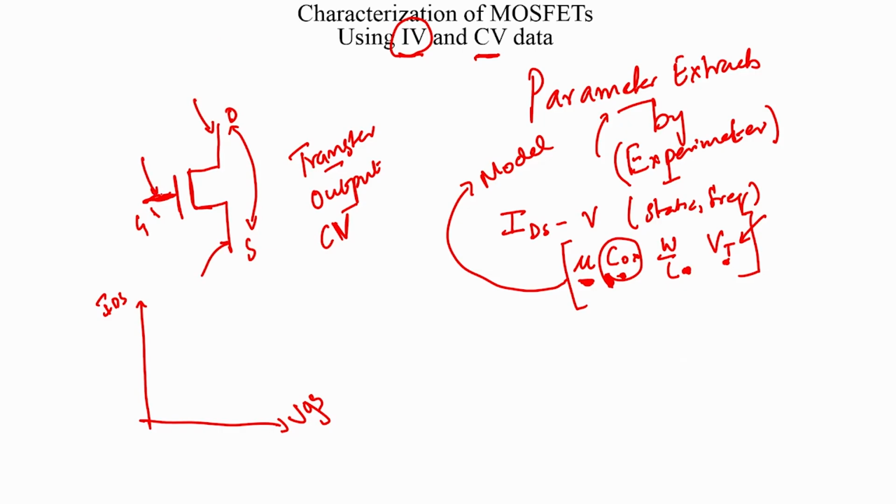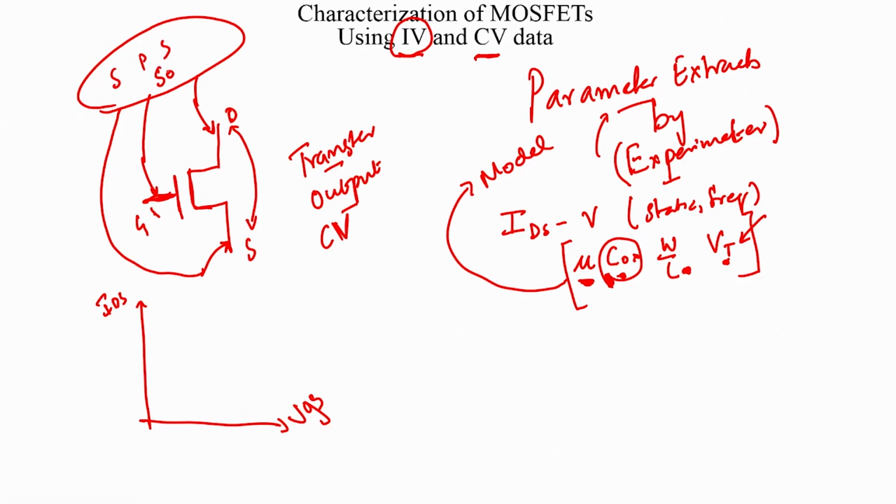Okay. So, make sure that these probes are all connected to high impedance. If you are going to measure voltages, they need to be connected to high impedance nodes, and if we are going to measure currents, you want low impedance. So, you typically want to be connecting these probes to a good semiconductor parameter extraction system, or very good quality source measure units.